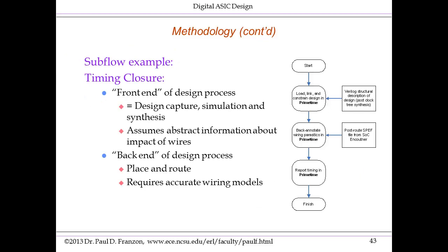I'm not going to go through all the steps in the back end, but I do want to very specifically talk about one step that integrates both back end and front end, and that is to do with timing verification. The delays of the wires are a very important part of the total delay within the netlist. Obviously, the delays in the netlist consist of both logic gate delays, which are largely determined by the standard cells, and wiring delays, which are of course determined by the lengths of the wires that you end up with connecting the standard cells. So to get that information, we have to do what's called back annotating information from the actual layout.